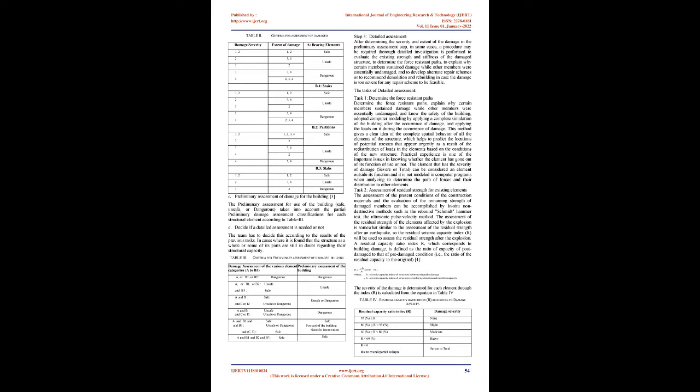Task 2, Verification of as-built construction. Objective: A. Thorough visual examination. B. Measure and record crack width, depth, length, location, and type. C. Surface defects such as spalling or scaling, shape, area, and depth. E. Corrosion of reinforcement, including the extent and amount of reduced cross-section. F. Visible deviations and deformations. Task 3, Condition survey of the structure.